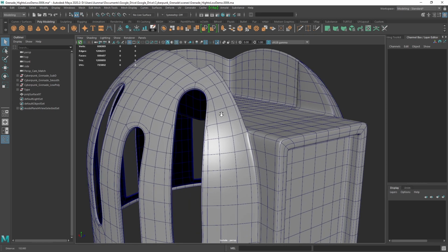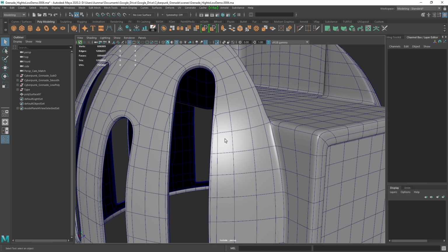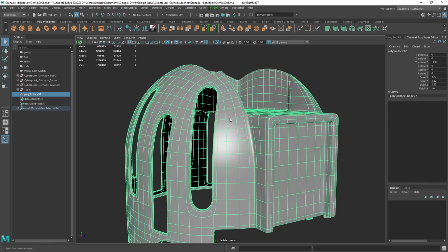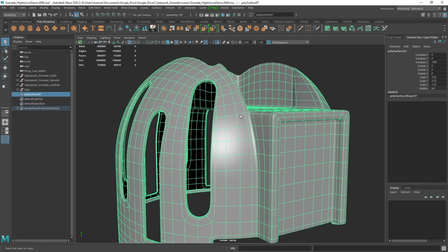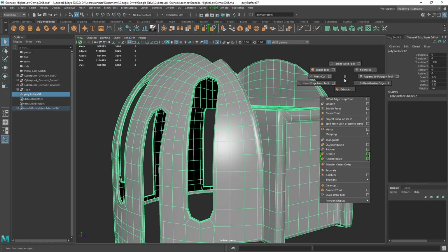So just keep that in mind, because the algorithms for essentially subdividing these triangles into quads are not as much of an issue, right? You have to be careful. Don't go crazy with triangles, but having an occasional one is completely fine.